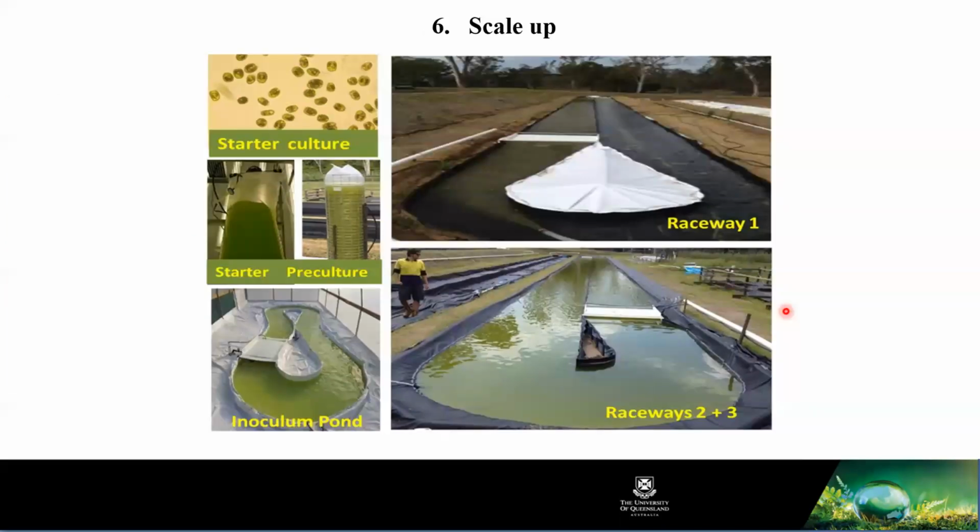And then once the bigger pond is in operation, we need to fill that with algae inoculum. How to do that? The pictures shown on the left are the starter culture of our algae, which is then scaled up in the laboratory in 250 ml to 1 liter flasks. Then it goes to the 20 liter bag, then the 200 liter bag, then the 2000 liter small pond, and then the 20,000 liter big pond before it goes to the 200,000 liter pond.